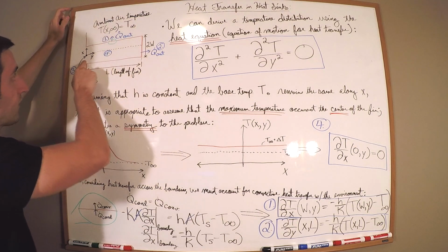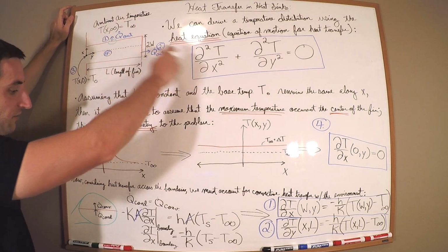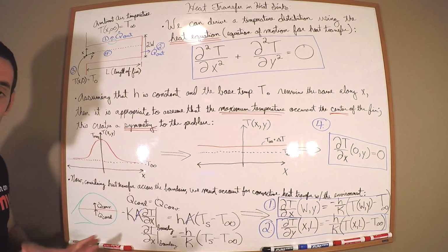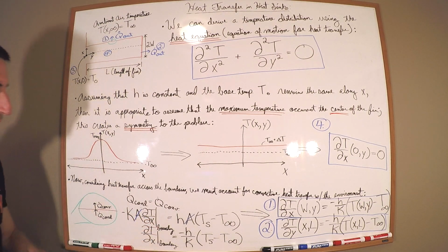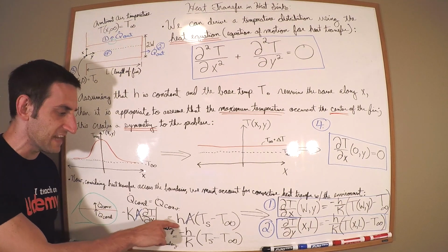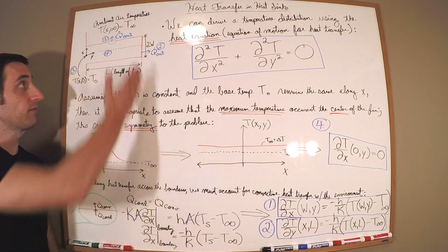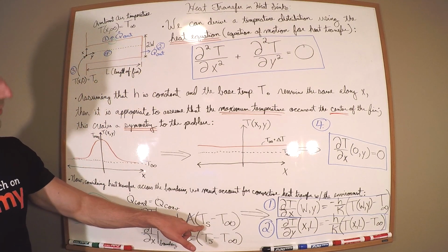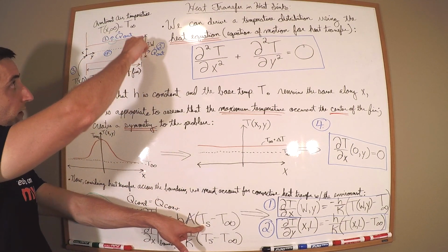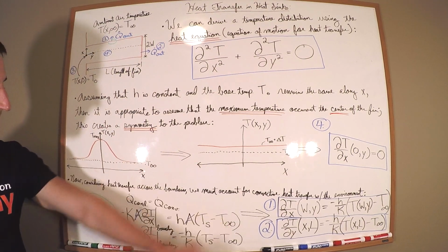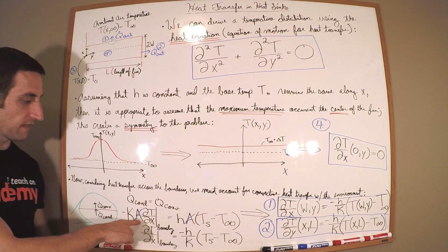This guy, we have to go in the y direction. So for now, I put dT/dx just to have some kind of derivative in there at the boundary. And we know that this has to be equal to the heat transfer coefficient h times the area it's flowing through, either that guy or that guy, times the surface temperature, which would be right here, right there, minus the ambient temperature. Okay? So if we take this, we know that the area is the same.